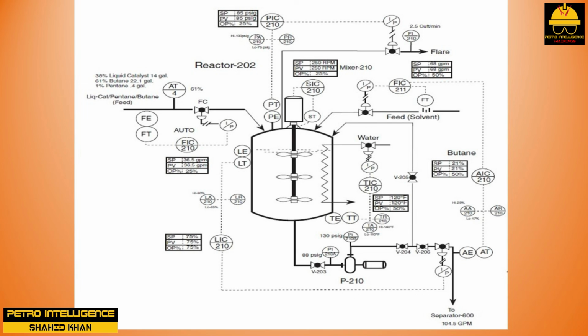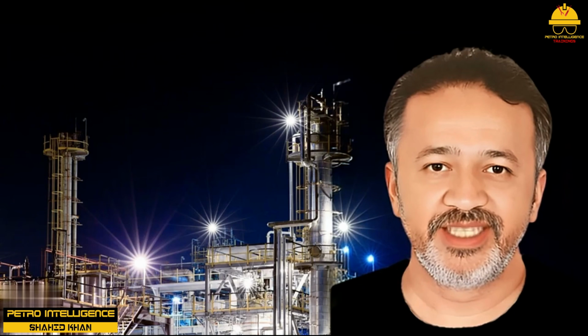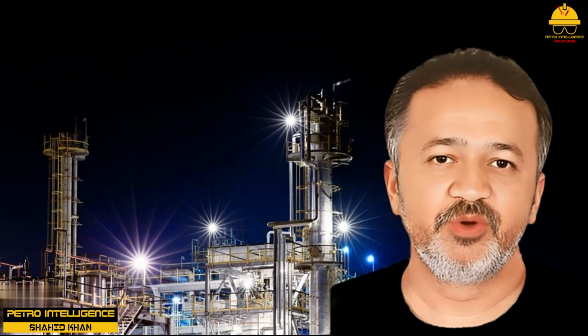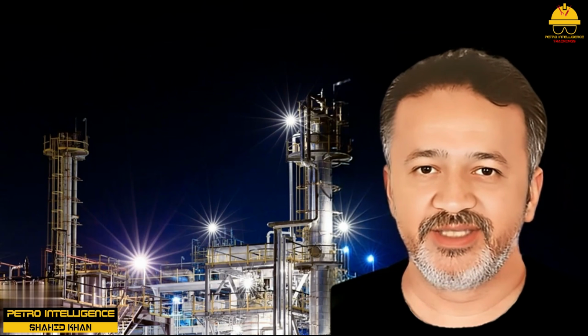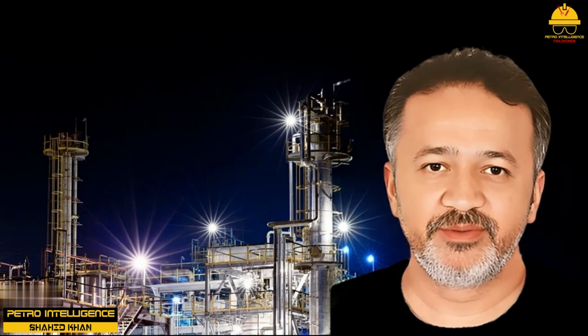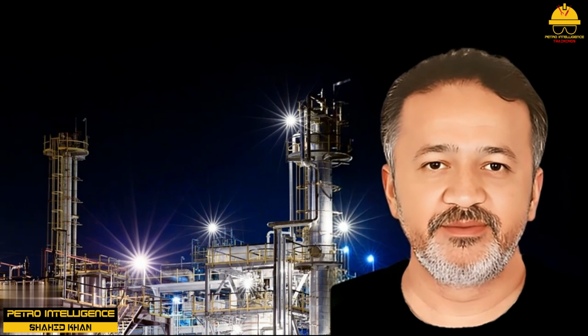The concentration of reactants in the reactor has a major effect on how fast the reaction will take place, what products will be produced, and how much heat will have to be added to or taken away from the reaction. A reactor is a device used to convert raw materials into useful products through chemical reactions. Heat, reaction time, surface area, concentration, pressure, flow rates, and catalysts and inhibitors affect reaction rates.